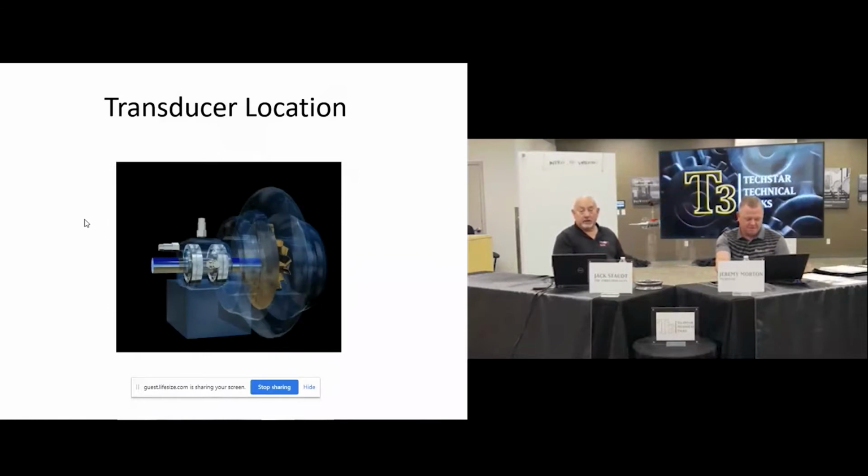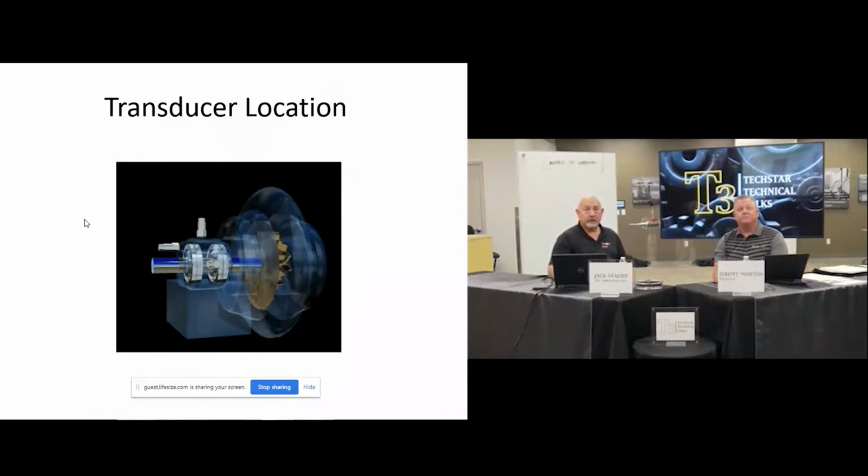So we're talking about transducer location. We want to do our XY, horizontal, vertical, and an axial. I was talking about the chart you might see.